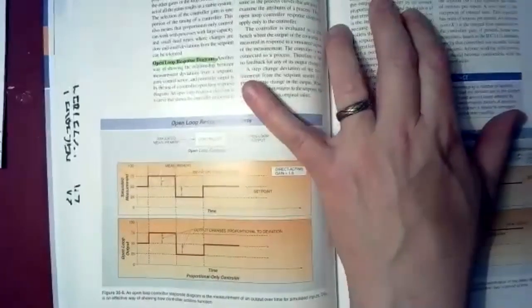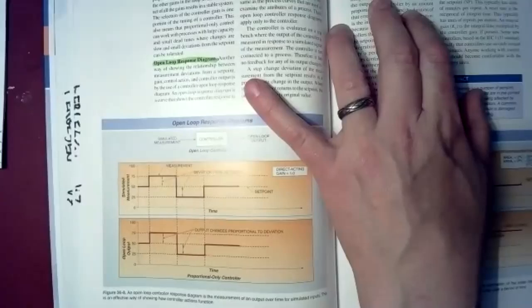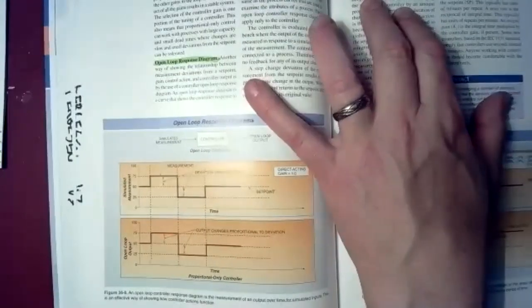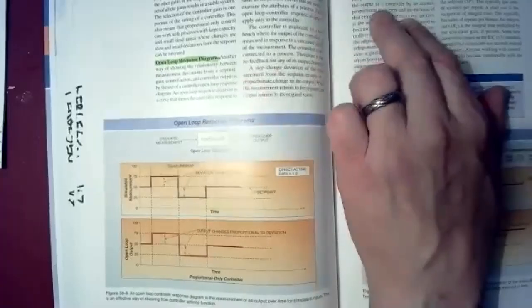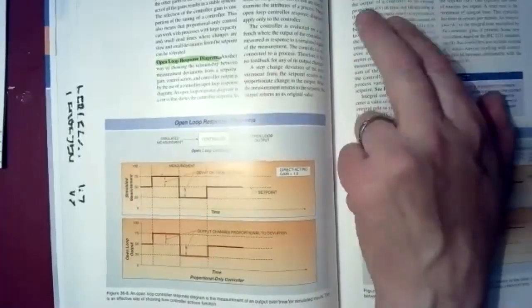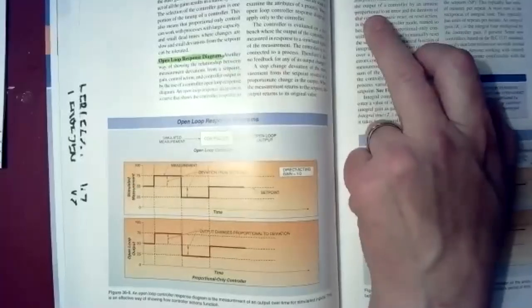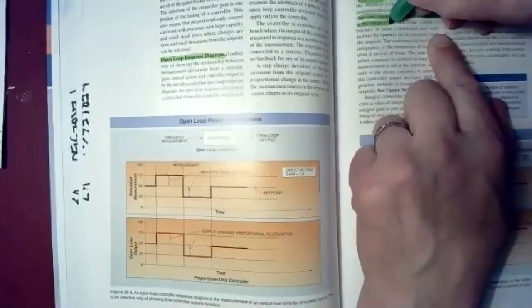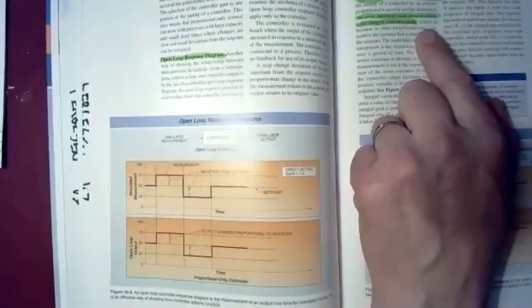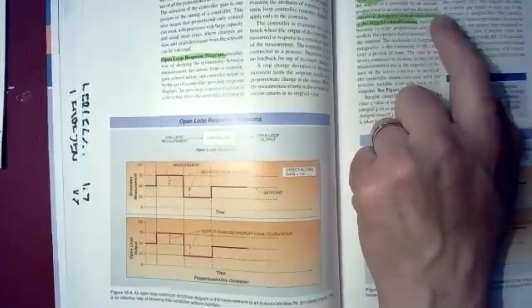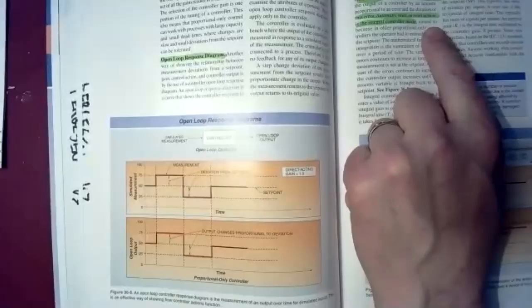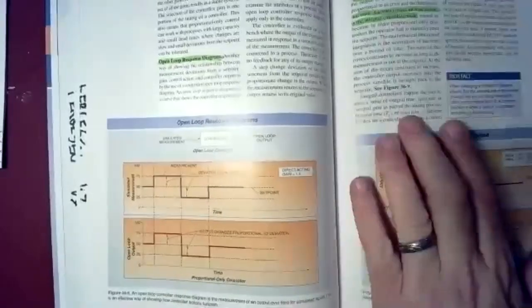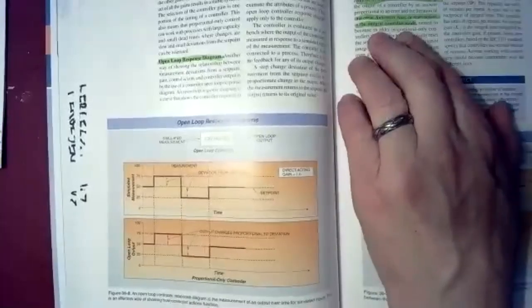So the next level of variable control, having an analog output for your control circuit, is integral control. It's a method of changing the output of a controller by an amount of proportional error and the duration of that error. So they're using a math function, not only how big the error is and how far off temperature you are, but the longer you maintain that error, the more your automatic formula calculates your integral control level.